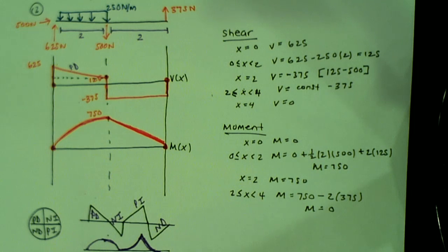The only times where I will use integrals or sections are if you have a point where the shear is equal to 0. So what does that mean if you have shear equal to 0? Good, you're going to have a maximum moment. So you have to find what the maximum moment is. For those of you who are civil, aero, or mechanical, and have to take solid mechanics or mechanics of materials, you're going to have to do shear moment diagrams and find where the maximum moment is. Whenever you have to do that, I would recommend using sections or integrals.